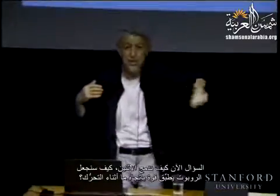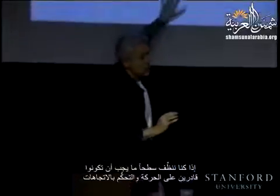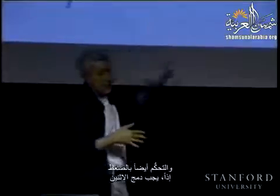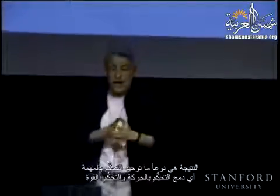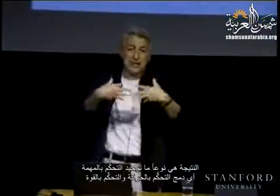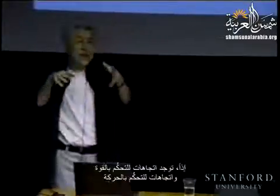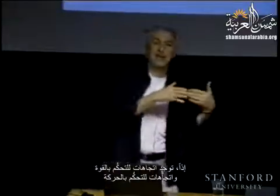We just dealt with the motion control. The question is how we combine the two, how we get the robot to apply a force in some direction while moving. If you are cleaning a surface, you need to be able to move, to control directions, and also to control the pressure. So you have to combine these two. And the result is a sort of unification of the task control in terms of motion control and force control merged together. So there are directions of force control and there are directions of motion control.